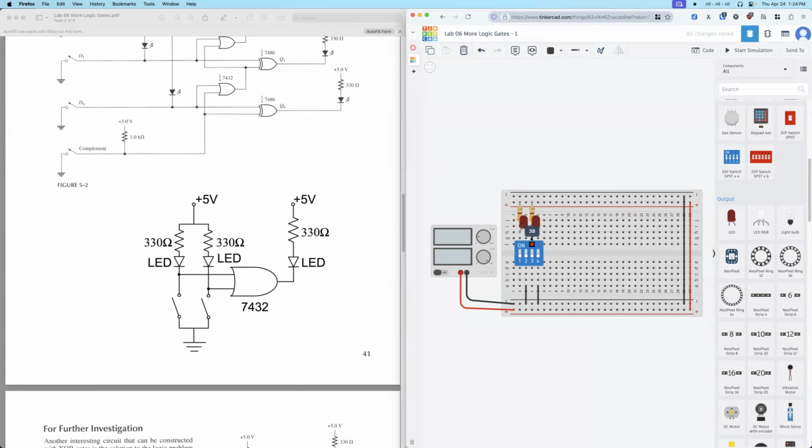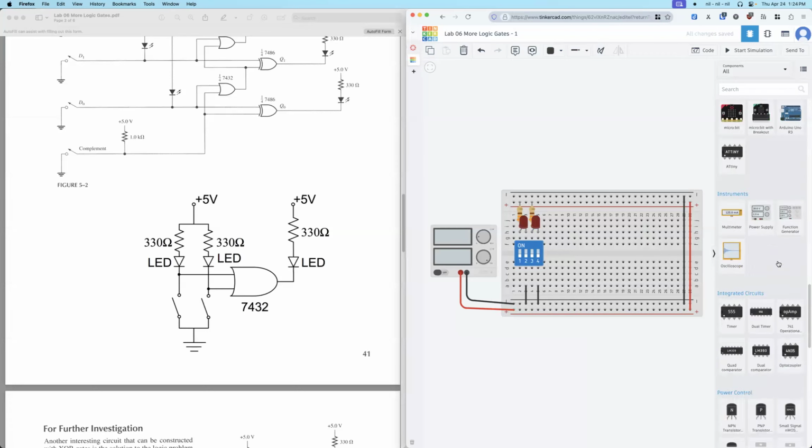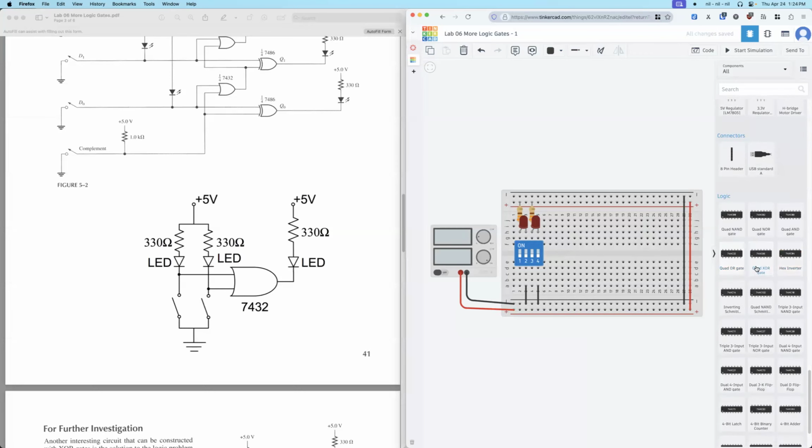Okay, let me double check. Okay, then we have, yeah. So now we can use these lines to connect to the chip. So 32. So I need to get, this is 32. So any position. So 32, first let me connect pin 7 to ground, pin 14 to power. So this is red.